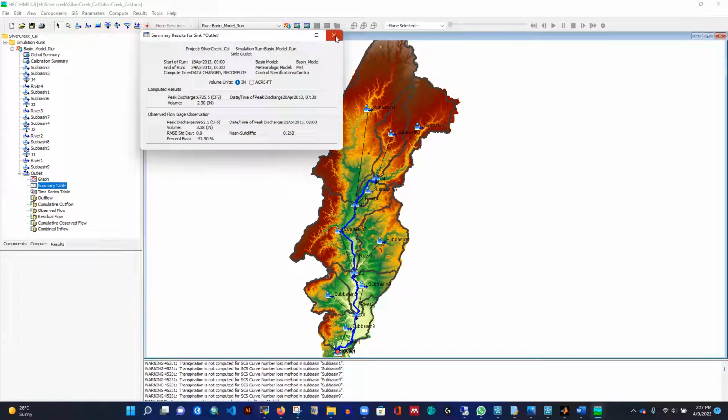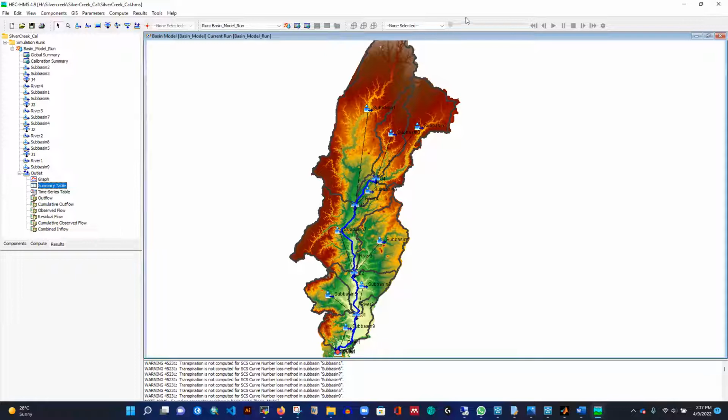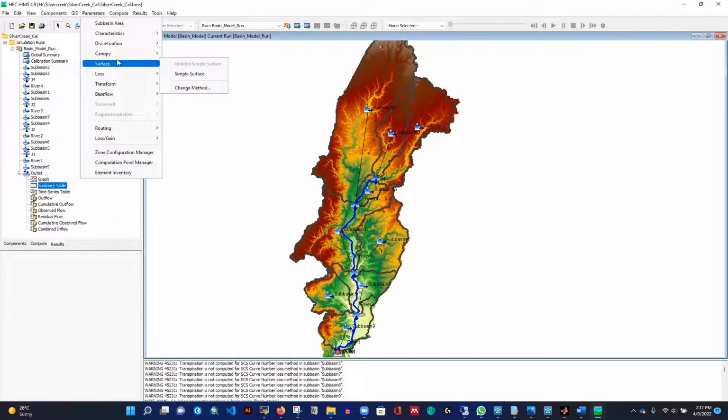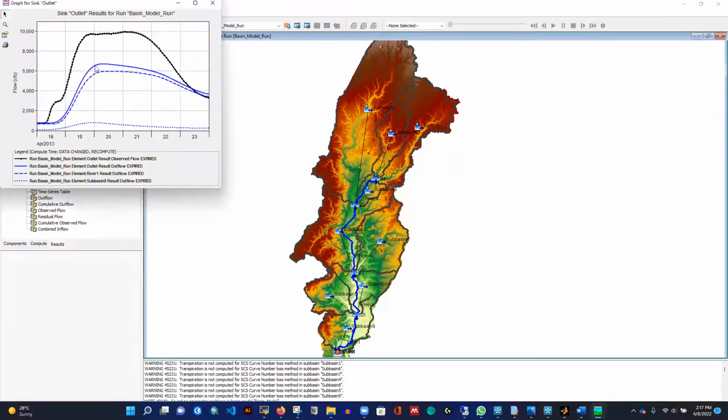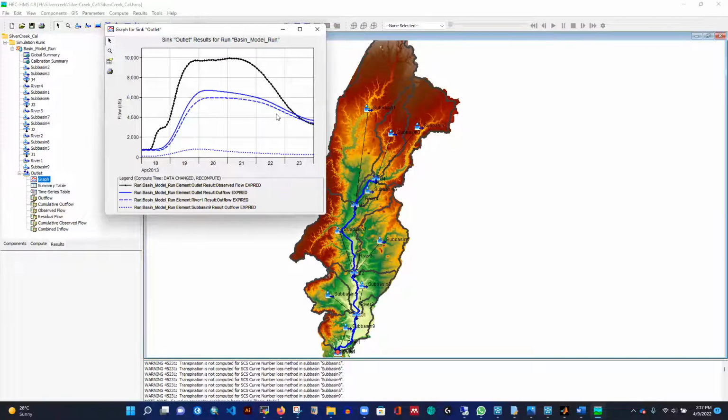So our model is basically underestimating whatever observation we have. Let's see if we can even capture the shape of the hydrograph using our model. For capturing that one, I can try, although I don't know how to even approach the process. From my experience, I start with the loss, because this loss factor is very important. Our model is generating a hydrograph that is even lower than the observation. That means our loss is higher than the actual loss, so we have to reduce the losses, right?